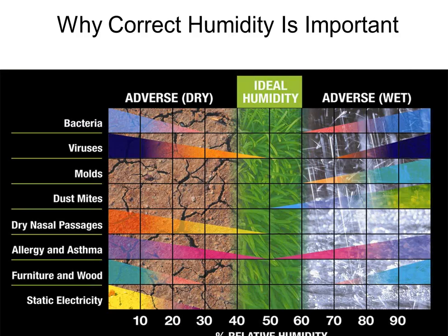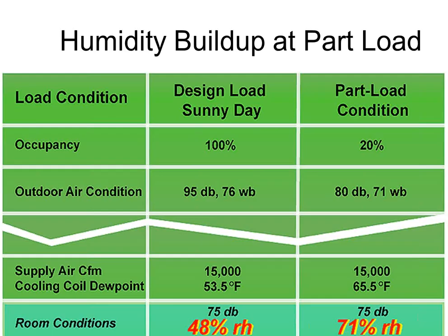We can definitely improve the humidity in spaces with an ERV by pre-humidifying and pre-dehumidifying the outside air. As you probably already know, lots of bad things happen when you get too dry or too moist conditions, and commercial buildings for the most part have neglected this issue for quite some time, and an ERV is going to help us with that. I'll just show you one example of what happens in a lot of buildings.